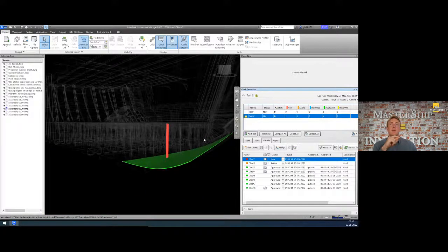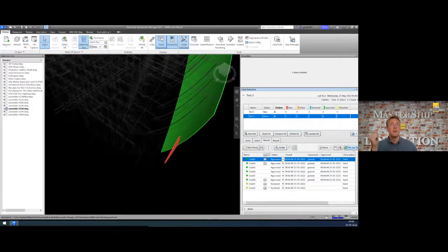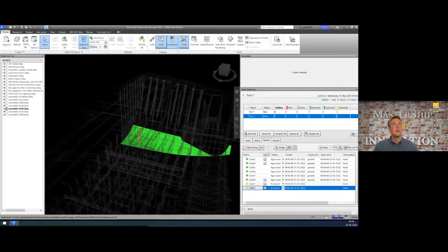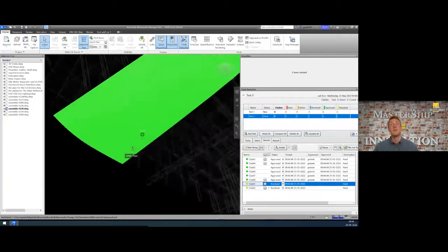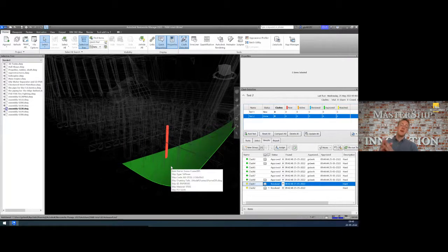And if we now look at our clash again, so here this was the clash, and this was also the clash. We do our test again. So we rerun the test, and there we see it. Clash 1 and Clash 2 are also both resolved. So that's automatically identified. We can take a look at it, but we can also just say, hey, they are indeed resolved. So we do not see it poking through the hull plate anymore. So we are happy.